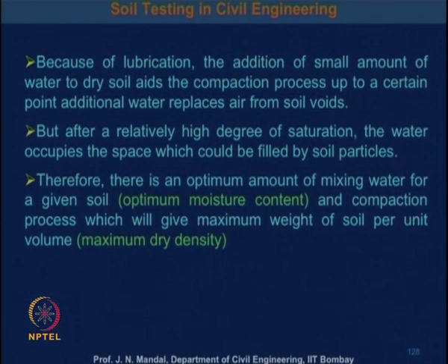but after a relatively high degree of saturation, the water occupies the space which could be filled by the soil particles. Therefore, there is an optimum amount of mixing water for a given soil.